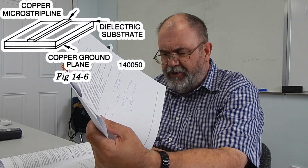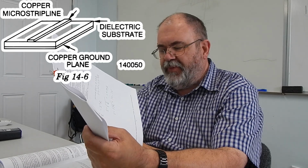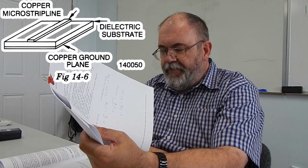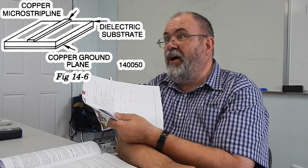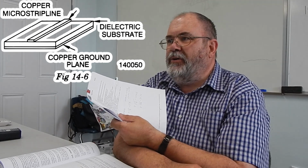Microstrip line, the top of page 14-10. Microstrip line is a form of printed transmission line. In other words, it's printed right onto a circuit board. They got a nice little picture of it at the top of page 14-10, where they show using a printed circuit board or PCB to make transmission lines, and the microstrip line is actually traces on the board used as transmission lines. Raspberry Pi uses those on the little one. Yep. Almost all the Wi-Fi Bluetooth modules in laptops and cell phones and Raspberry Pis use microstrip line antennas, just because they're really cheap, because they're just part of the circuit board design, and you don't have to add any extra hardware. You just use microstrip line.